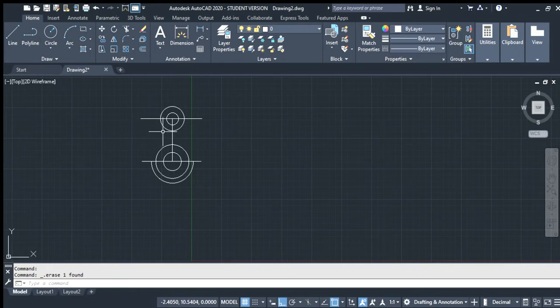So we'll go ahead and right click, left click and select both those, the circle and the line. Go up to the trim tool and we'll trim the bottom part of the circle, hit enter, and we're done there. We'll go ahead and hit L again, enter for line, grab this endpoint and connect it to that endpoint.